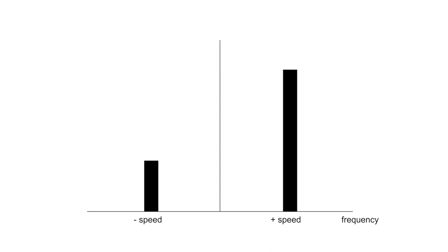Now please imagine the spectrum graph. It is a little special because it contains the positive frequencies and negative frequencies. The amplitude of motion in rotation direction we draw to positive part. The amplitude of opposite motion we draw to negative part. This spectrum is called full spectrum. Splitting of amplitudes to positive and negative frequencies contains additional information for analysis.